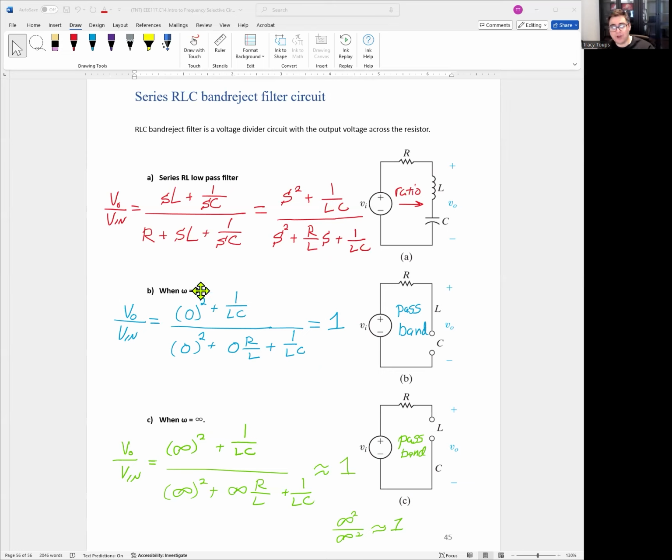Oh, and then the gain of the circuit is output voltage compared to input voltage, where we're doing the resistor voltage division, except we're across the inductor and capacitor this time. So you can just do the math here. You're going to have the inductor impedance plus the capacitor impedance divided by all three impedances put together. We could just do some number crunching to make things look nicer.